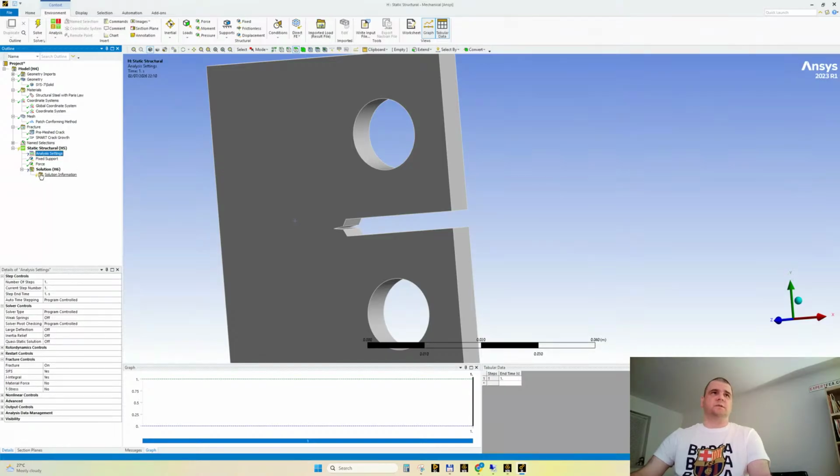So let's go here. It always shows a question mark because it does not accept finding the J integral together with the stress intensity factor. You need to choose one of these. This is why we make this one now. You see the question mark disappeared. We leave everything like it is. It's not a large deflection simulation. You'll see the displacements, the total deformation in the end.